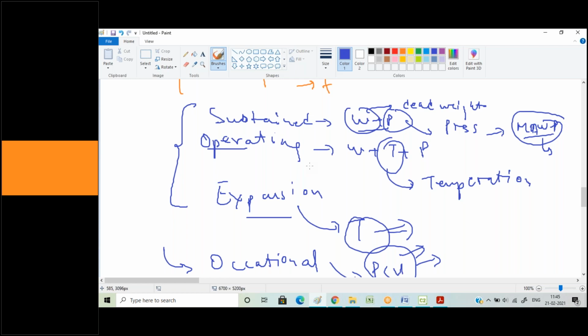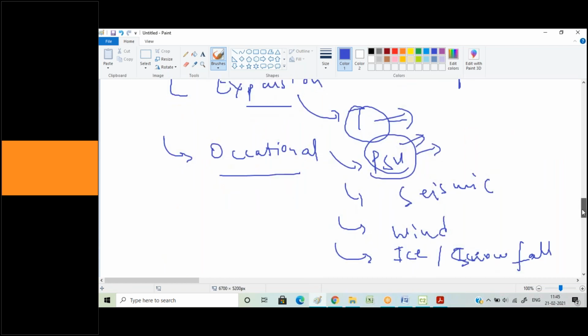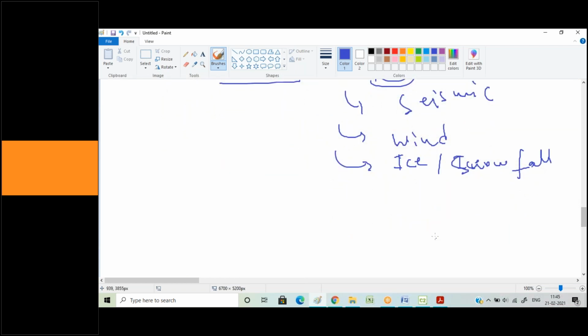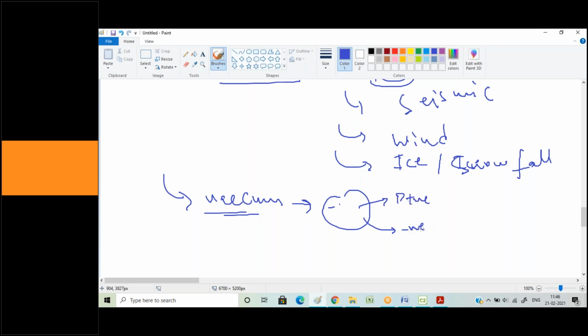Anu, what about negative pressure? If I have negative pressure, can I fit it in sustained? Obviously, in case of vacuum, yes, you can use that. If you're having a negative pressure and also a positive pressure, you can basically make two design cases: one for your positive pressure, and the other for your negative pressure.